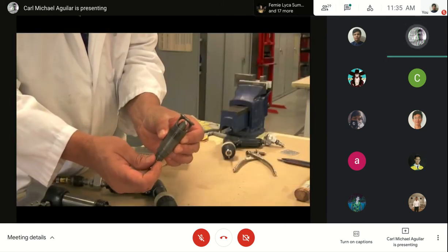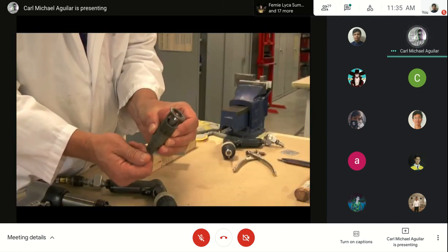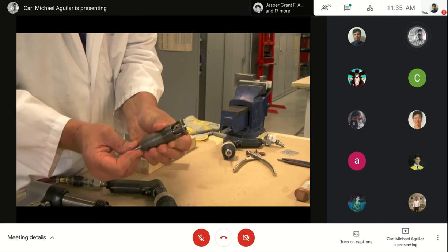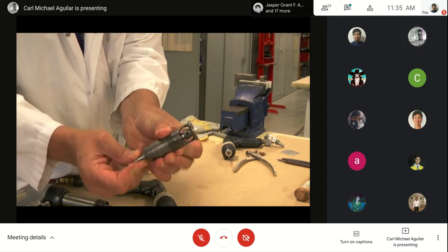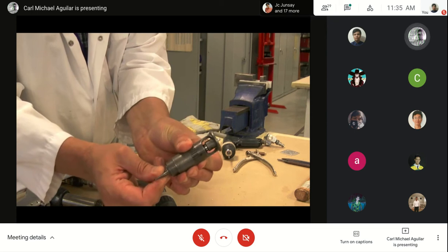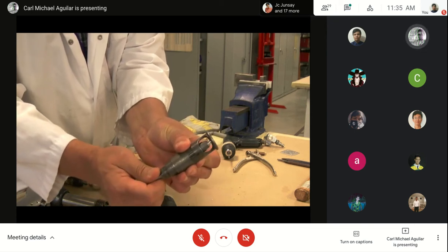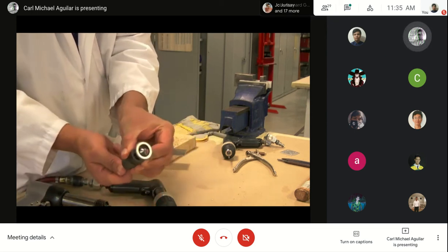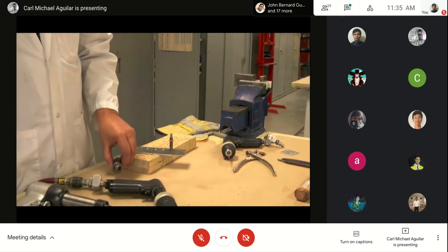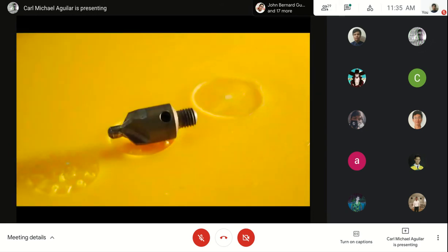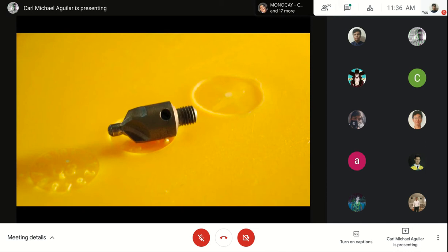The microdial, also called the microstop, features a rotating extensible shaft in a fixed body. The shaft allows for installation of different cutters and rotates on a set of bearings in the housing. Each cutter has the same 1/4 28 thread form and offers nose pilot pins sized the same as our solid rivet diameters.